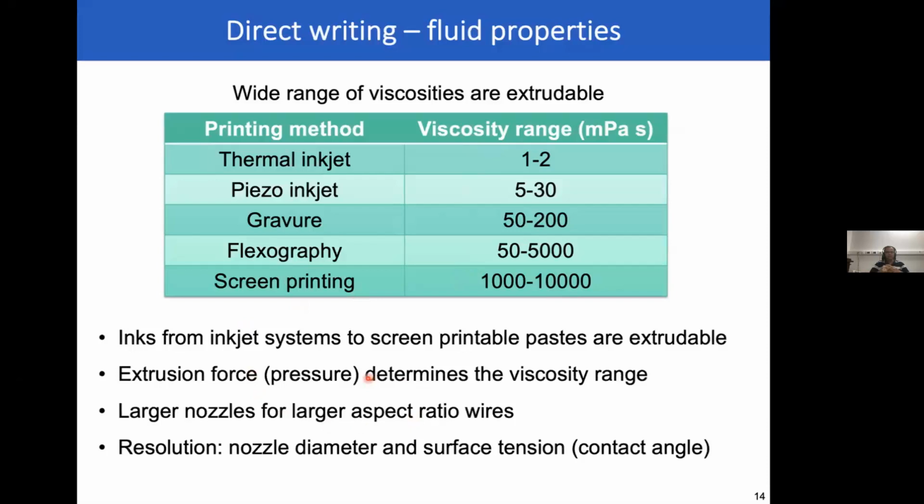We can also use nozzles of different diameters. Especially for the longer wires, I can print or deposit them by just using larger nozzles. Of course, the drawback is that larger nozzles will have poorer resolution.